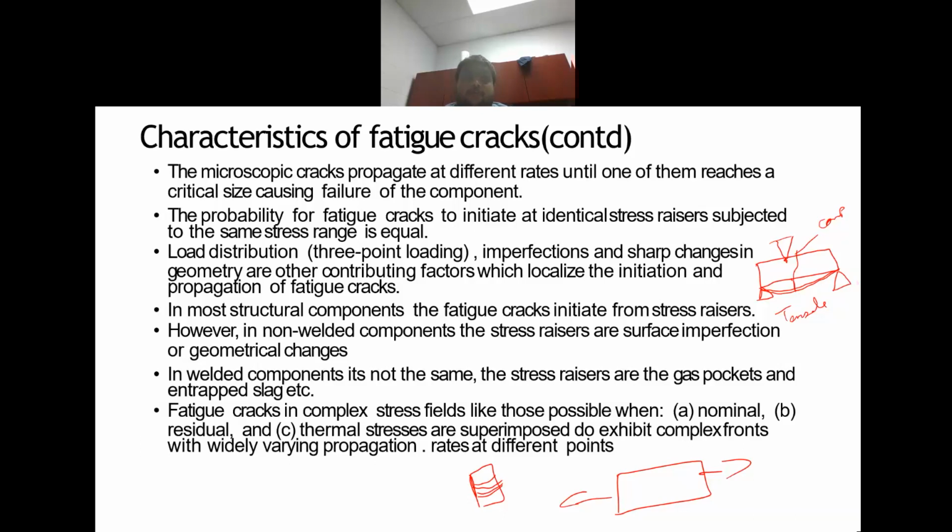I'll talk about this later in detail, but you will see some lines that are found on the surface and you can actually feel it. And because of those, all this stress raising or the dislocation that you see on the surface, the roughness of the material starts going up. Once the roughness of the material starts going up, that becomes the stress raiser, which is causing a stress concentration because of all the roughness that you have, and that is going to cause a surface crack, and that's how it kind of grows.